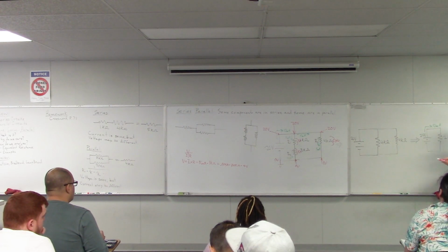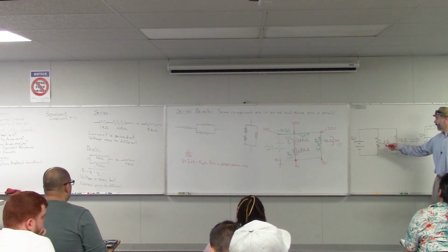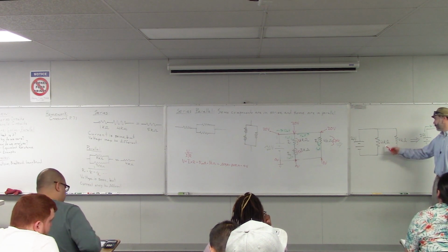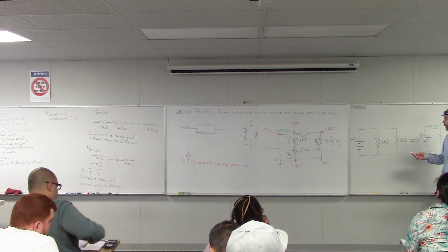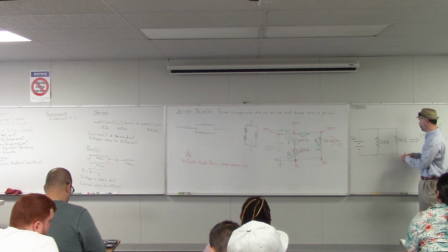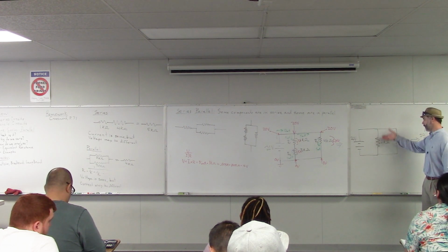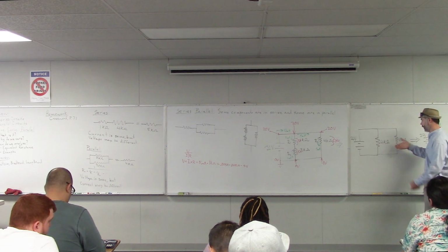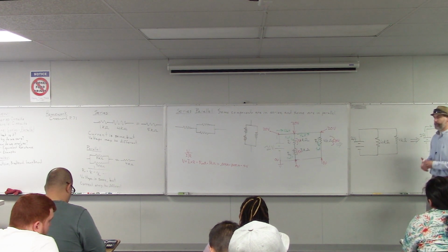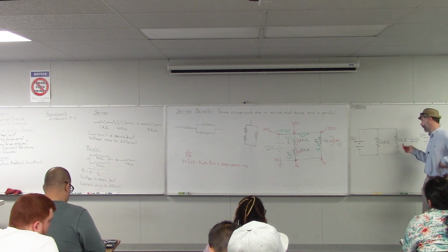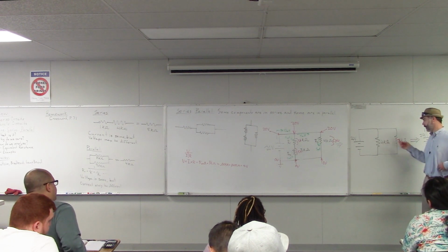Well, when we found the equivalent resistance for those 2 branches, we found that both of those branches had an equivalent resistance of 4 kilo ohms. And that's really why the current was the same in both of them. So if you saw that each branch has an equivalent resistance and they're in parallel, then that's when they would have the same currents. And if the resistances had been different, that would be an indication that the currents would be different.